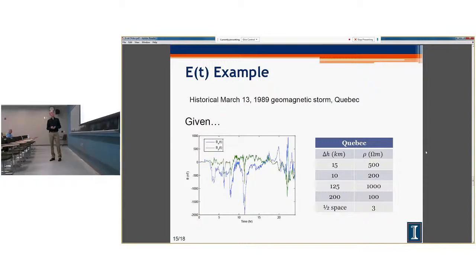So here is an analysis of the storm I was talking about at the beginning in Quebec. This is the B field data, the magnetic field data of the Earth and how it's changing over the length of the storm. To give you a ballpark, the magnitude of the Earth's magnetic field is about 50,000 nanoteslas, and this is changing on the order of 2,000 to 1,000. So that's like a 3,000 swing in the span of 24 hours. This is what causes the currents to flow in the grid that we don't want. These quick changes and oscillations back and forth are what do the damage.